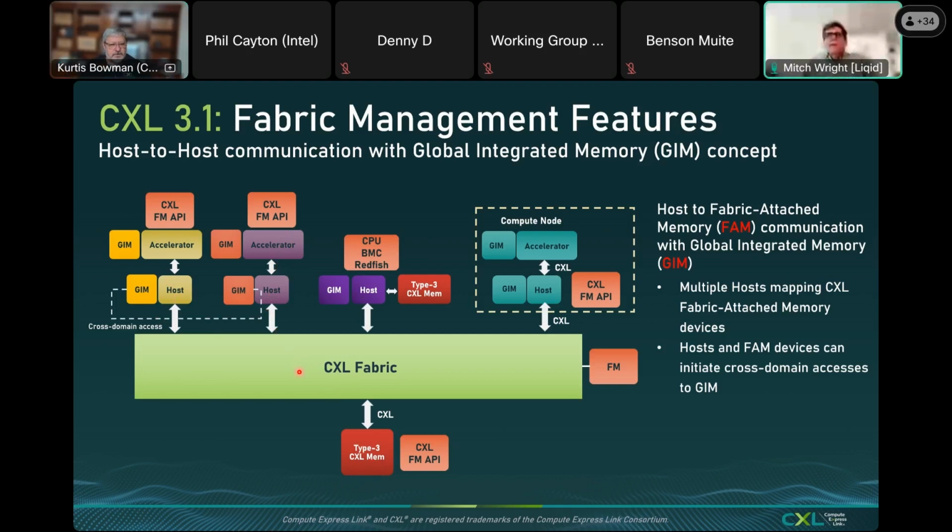Yeah, CXL shows up as system memory. So the traditional or legacy GPUs that are on the PCI Express bus would see the memory just as though it's system memory. And there is not a GPU specifically, but there is an FPGA supplier with a very high performance CXL interface. So there is the capability of doing acceleration devices today with CXL directly attached.